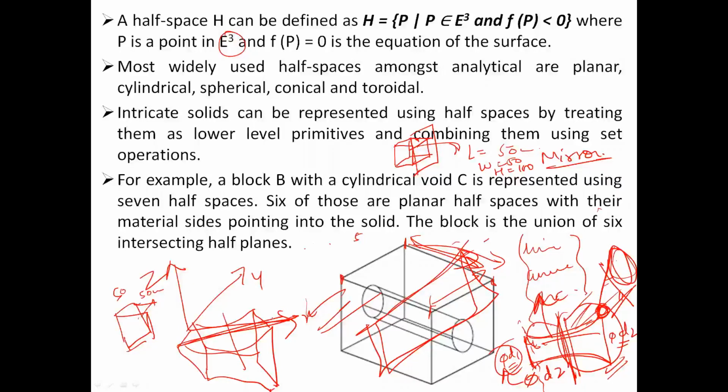The same thing is happening as in the previous method, primitive instancing: you need to visualize the product very clearly before you even make a CAD model. The images should be very clear in your head. You will have six or seven images, front view, top view, side view, isometric view, all in front of you. You need to merge those images together in your head, get a three-dimensional image, and then think about doing the planing. That is the difficulty with this process.